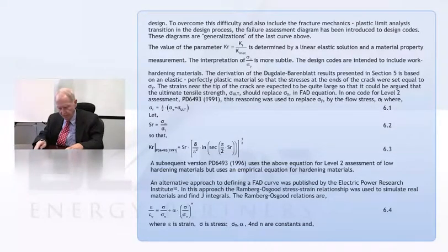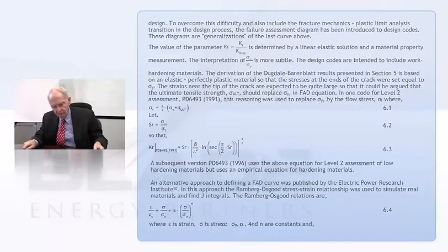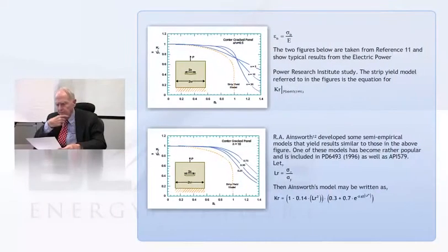So epsilon is the strain, sigma is the stress, and sigma 0, alpha, and n are constants that you cook up in Anderson's book. It has pictures like the inserts on this curve for all kinds of loads and combinations, and then that book that gives the stress intensity factors has just got tons of that stuff.